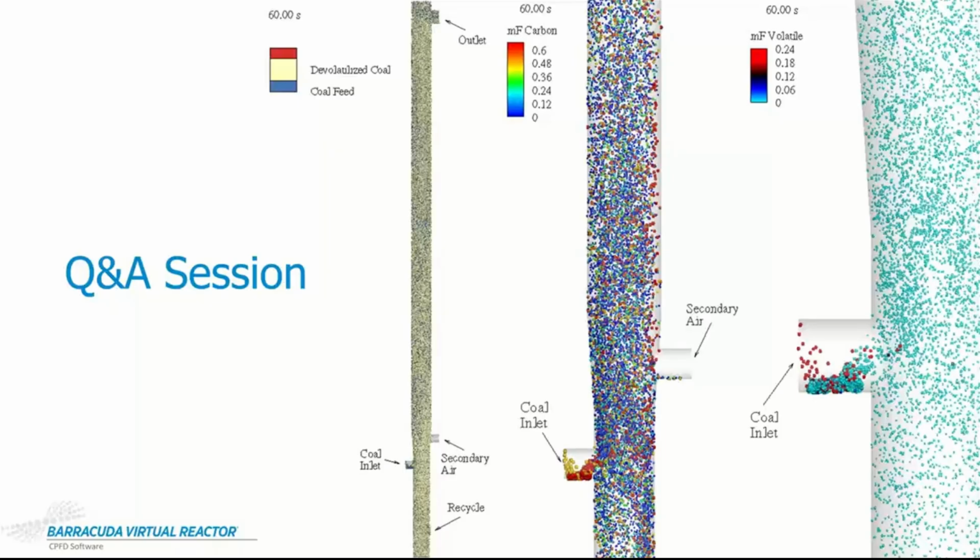I guess it boils down to how the particle interactions are treated. Essentially, in DEM, these are resolved on a more explicit scale, whereas we use particle stress models within MPPIC to resolve that. Again, the difference is that DEM, while it can be more accurate on smaller scale models, scaling up is a challenge when you start accounting for particle-to-particle interactions where you have tens of millions of particles, and that is where MPPIC truly stands out. It's not only accurate enough, it's also scalable.